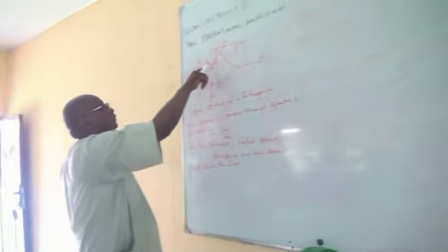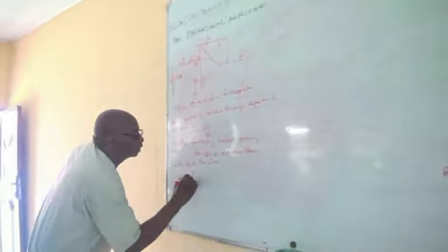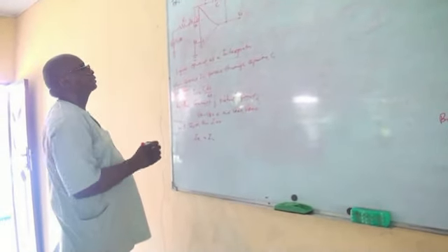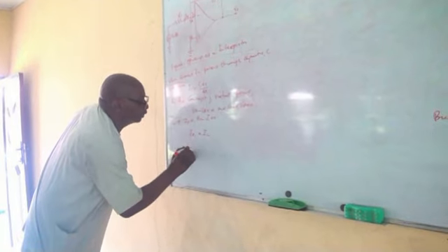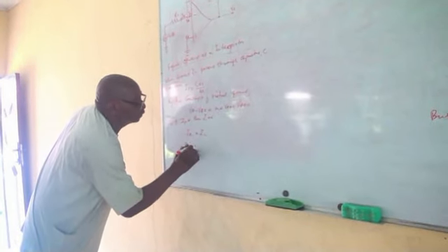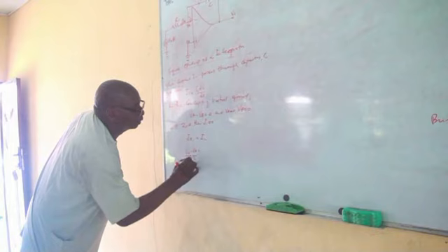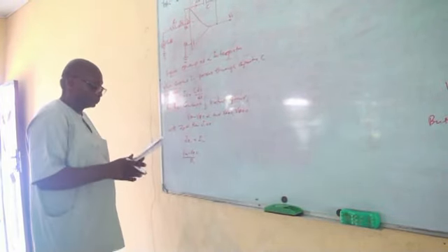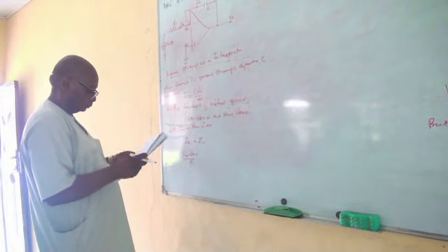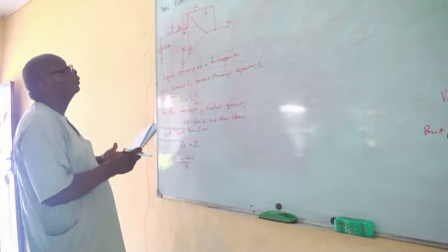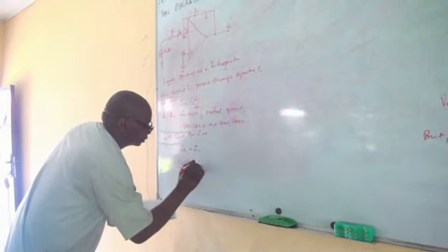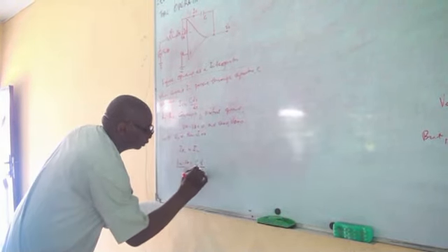Therefore, the currents we have here, IR1 and IC, right? IR1 equals IC. So what is IR1? That is Vin minus VA all over R1, equals to C dV over dt.